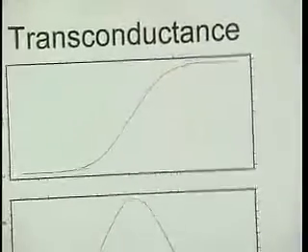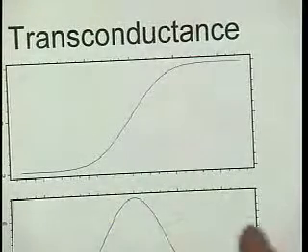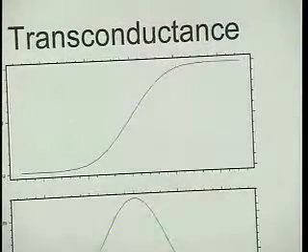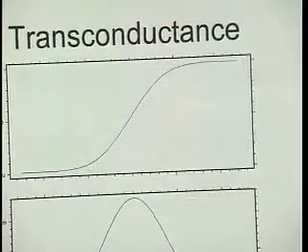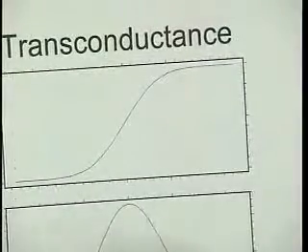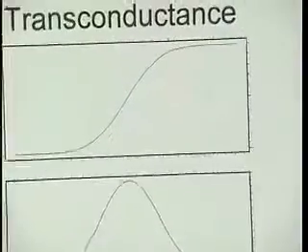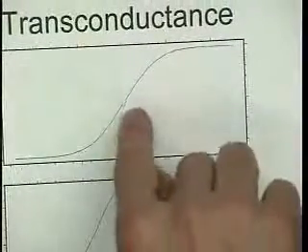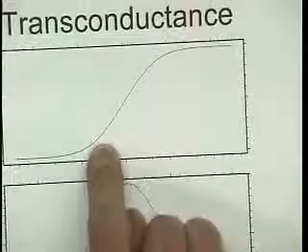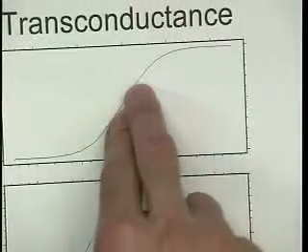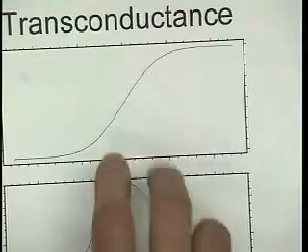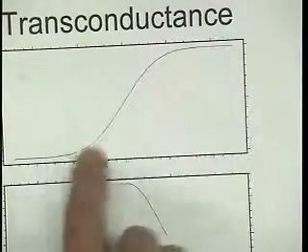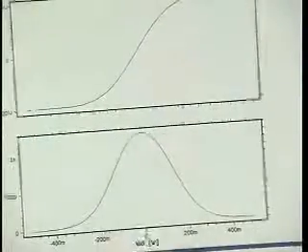Here is the output transconductance, right? I guess I could have looked at what I designed for and come out with something. And also, of course, the transconductance rolls down because the transconductance is simply the slope of the differential current that flows into the output, which I short circuit in this case, and as the slope drops, so does the GM, right?